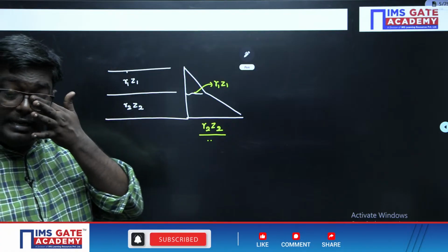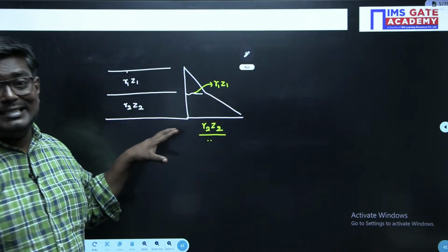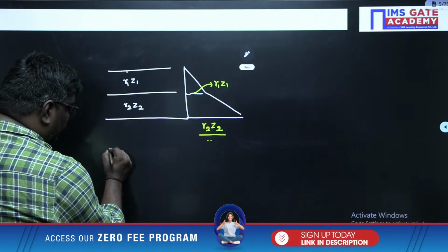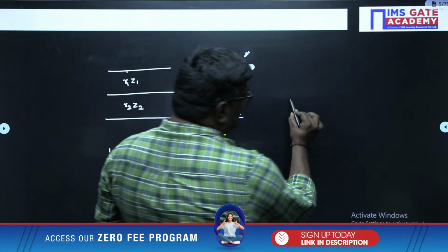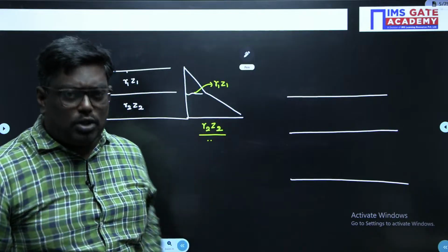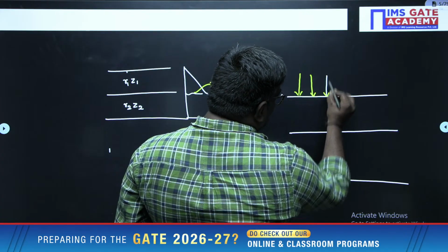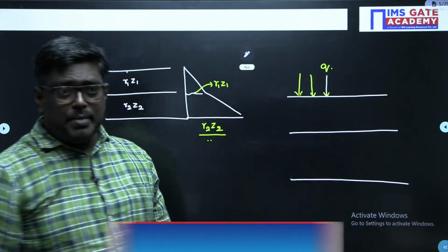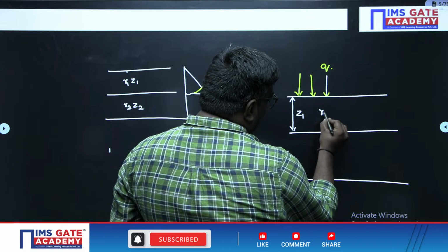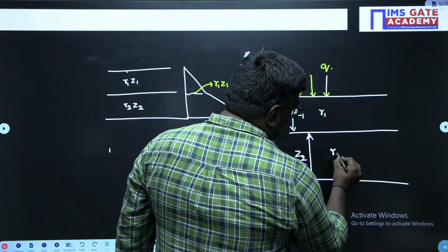Right? So, my dear students, the first step is calculating the coefficient of earth pressure. The second step here is the calculation of total stress. Now, when I tell you calculation of total stress, let me give you a generic case where we can come across everything in this question. I am just talking about the vertical stress here. So, here we have the surcharge, and remember, here we have a depth Z1 and a gamma 1 here, and this is Z2, and here we have gamma sat.